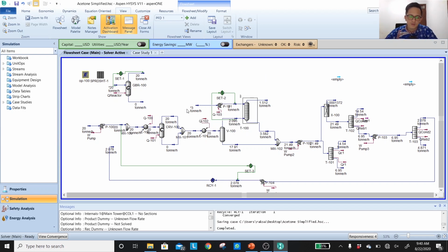Okay, if you need one example, for example, now we are guessing the number of this water in the stream to be 3 ton per hour. But you can imagine once this recycle stream is combined into the mixer, it will add the mass flow rate of the rest of the stream. Instead of 20, maybe it's going to be 22 point something ton per hour, and that will obviously affect the equilibrium in the absorber. So it's up to you.